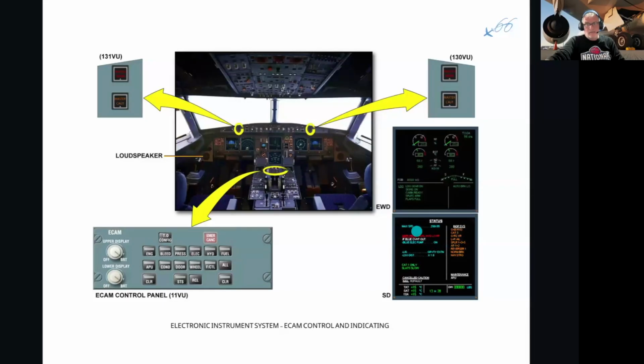Okay, and you can see some advice, some QRHs, some advice to the pilot in terms of a defect. So this is the general layout of how a status page would look. Okay, and there is also, if there is some stuff in this section here, which is usually for class 2 faults, you'd get a maintenance, a system in maintenance in this status page as well.